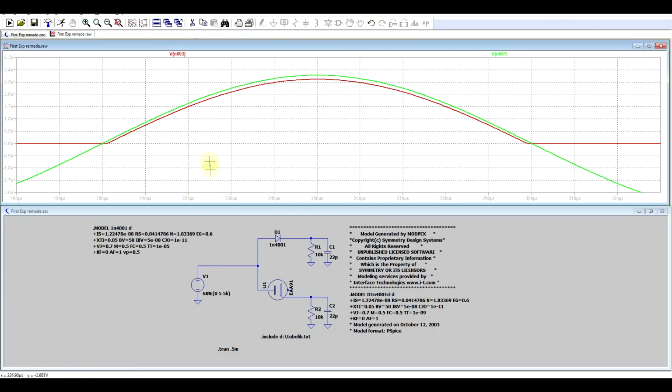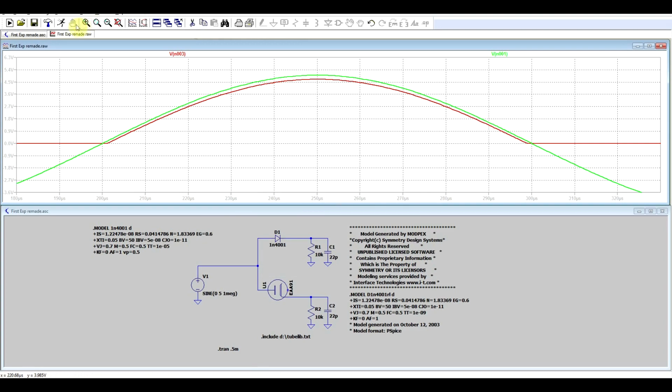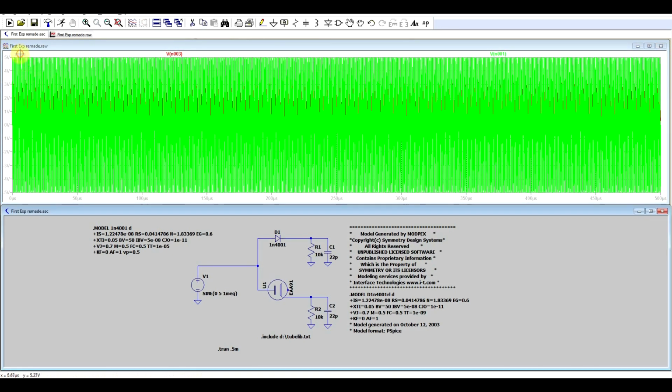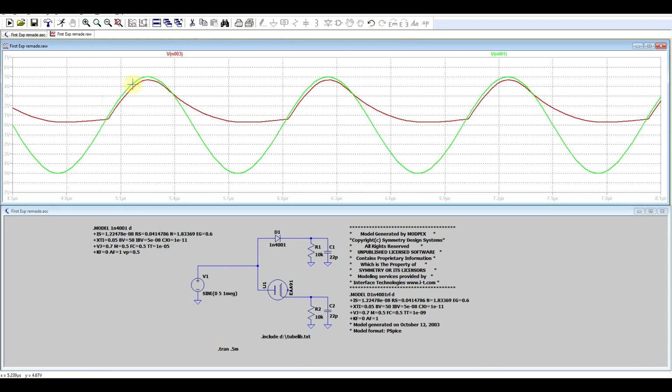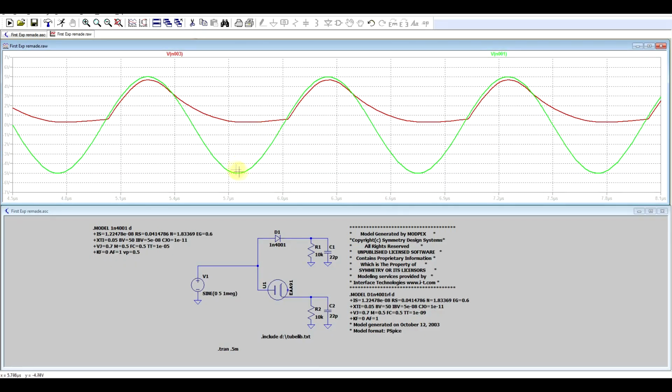So just to make sure, I performed one more measurement in which I replaced the 5 kHz sine wave with a 1 MHz sine wave. So first of all, let's see what the simulation predicts. I'm leaving the same 5 volts amplitude, and now if we look at the output, we see that the output voltage no longer goes down to 0, so there's a nice decay here. This is basically because of the capacitance added to the output of the circuit. And also when the negative voltage starts to rise, so does the output voltage. This is basically because of the capacitance of the vacuum tube itself.